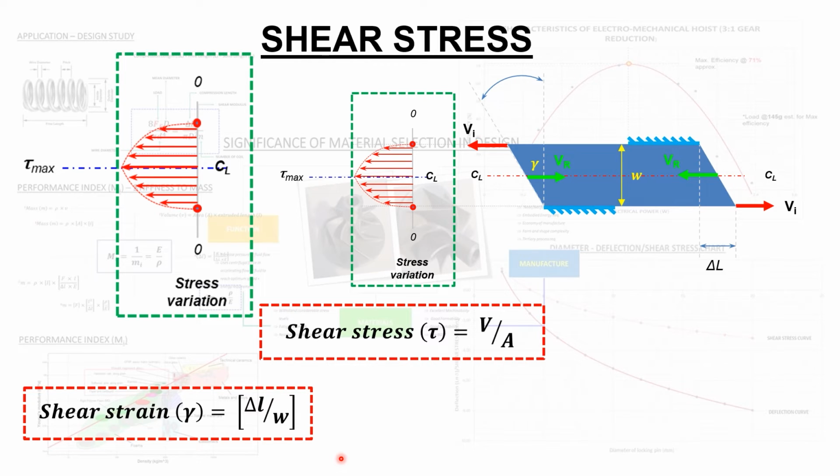So again, it's more or less up to you whether you want to denote the unit for shear strain as dimensionless or denote the measure of shear strain in terms of radian. Radian is spelled R-A-D-I-A-N, in short R-A-D or rad. So we have to be very careful that we don't express gamma as a degree. What you have to do is calculate for gamma and convert from radians to degrees. We'll look at similar situations when we go through our worked series relating to shear stress.